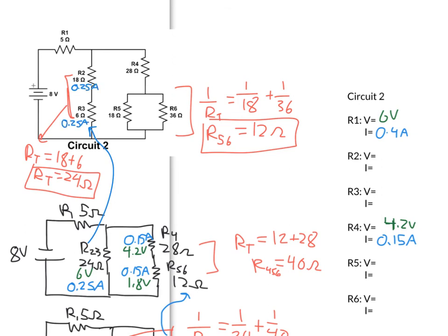And I can use Ohm's law then to get the voltage that's going to be on each of them. So I would find that R3 would be 1.5 volts. And then R2 is going to be 4.5 volts. So I can add those over here to my overall chart, 1.5 and 4.5 for 2 and 3. And both of them get 0.25 amps of current here.